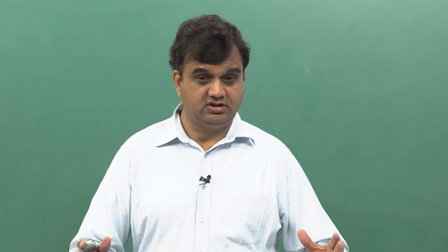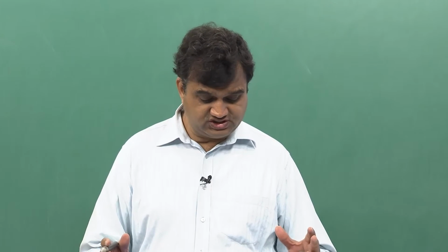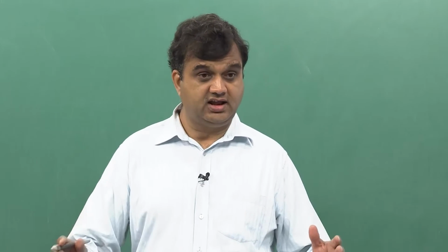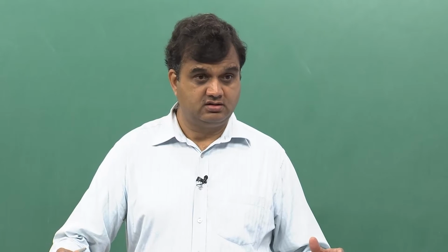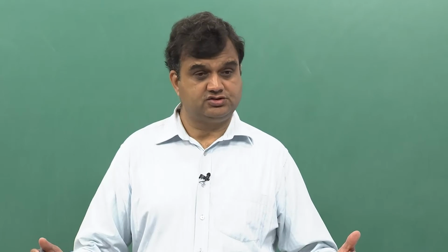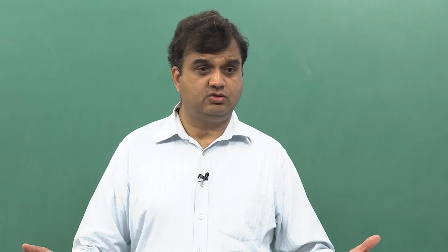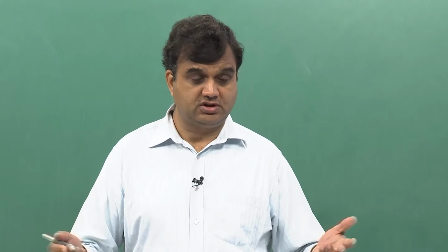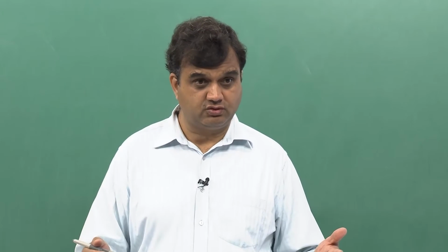I do not have to solve for the whole domain. What that means is that if I require 4n elements for the entire domain, then if I am only solving for 1/4 of the problem, I need only n elements. So, my computation will be faster because the number of equations will go down by a factor of 4.